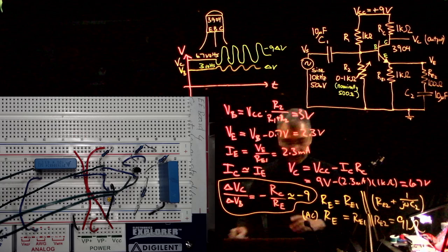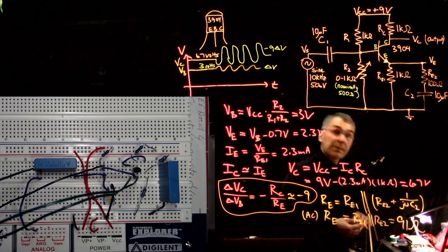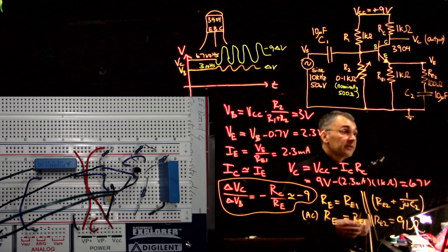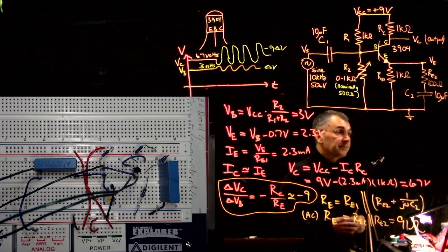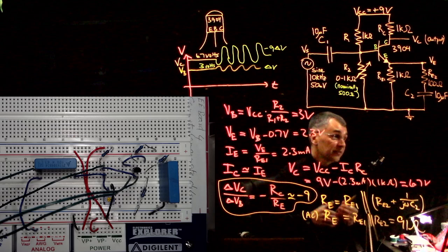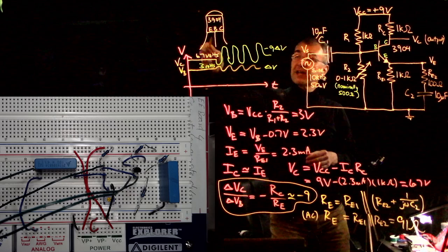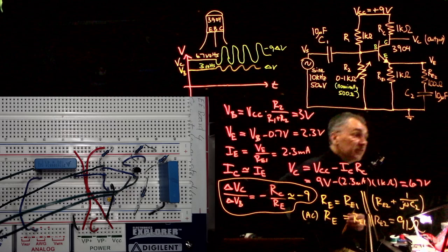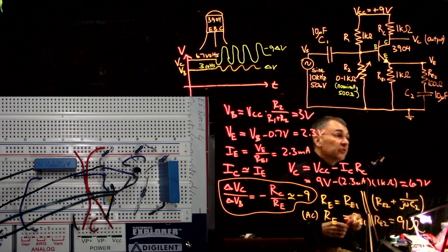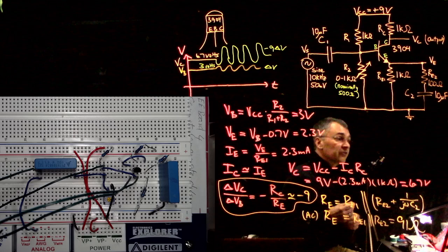What else do we have here? So now remember these 2N3904 or later 3906 transistors, the naming convention is EBC. Transistors are as easy as EBC. So emitter, then base, then collector. When you're looking at the flat side, the emitter, then the base, then the collector. So that's not always the most convenient for wiring things up if you want your circuit to look like your schematic diagram.